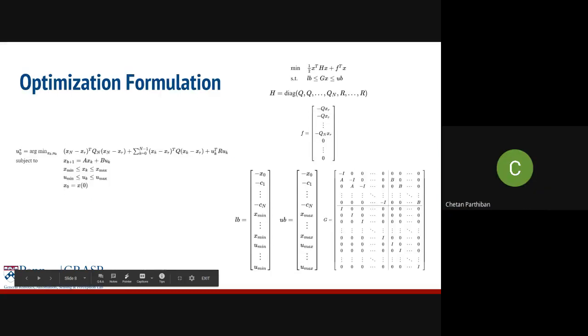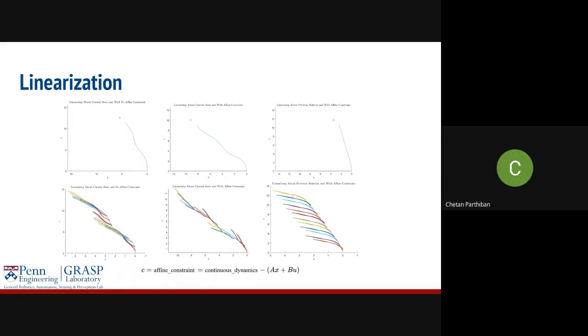Yeah, and I guess for us, sorry. Oh, go for it. I was going to say, one of the things we struggled with for a while in figuring out, and these bottom plots helped us look at, was our earlier plots. On the ones on the left, you can notice that the RRT planned paths are not tangent with the curve to start off. That was part of what was causing our model to jerk and oscillate. One of the really good advantages we found when linearizing around a previous solution is that our MPC paths are really good at starting tangent to our current trajectory. That really helped tracking in the simulator a lot.